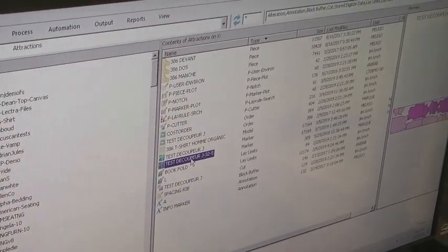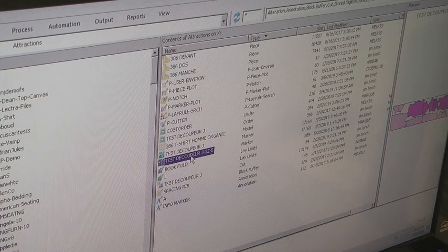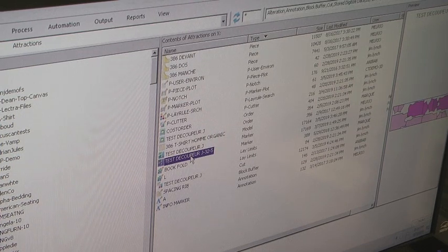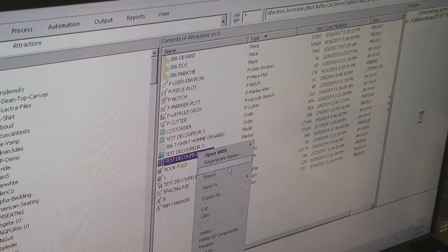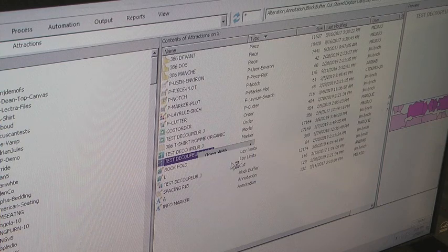We're going to generate a cut ticket in order to spread with the XLS125 using the CAD interface, which will allow us to have the spreader automatically set the correct distance, and we'll have splices in there, and we can also use the label ID. So from AccuMark Explorer, I'm just going to right-click on the marker to generate cut data.